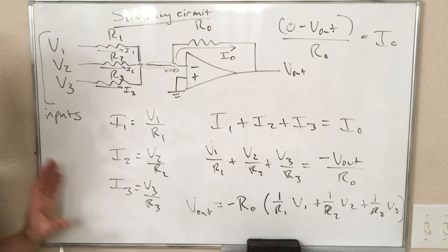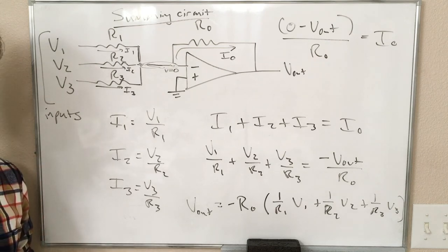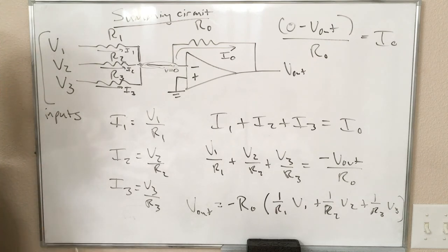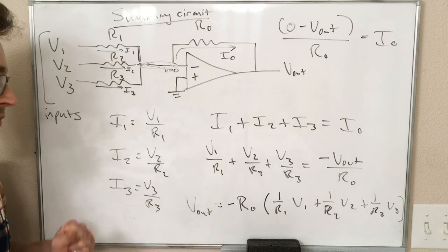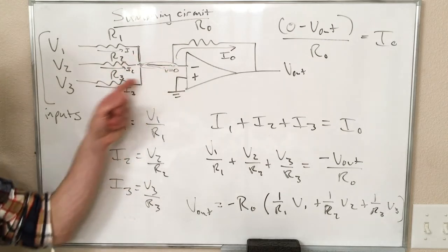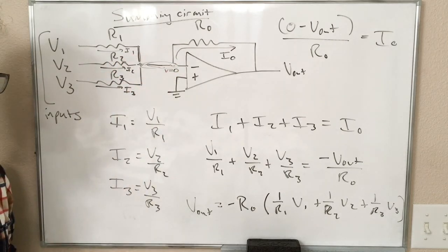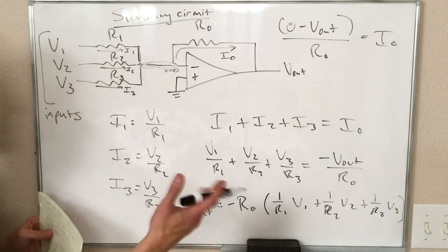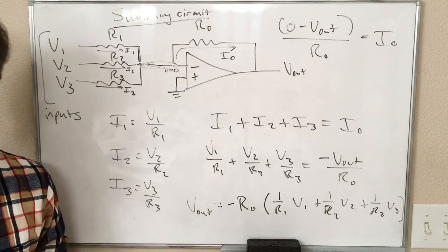Anyway, the conclusion of all of this: our op-amp golden rules make it very easy to analyze complicated circuits basically just with Ohm's law. Other than the golden rules, Ohm's law, and a tiny bit of Kirchhoff's current law here, that's the only thing we've had to use, and we've gotten some really neat results for some pretty complicated op-amp circuits.